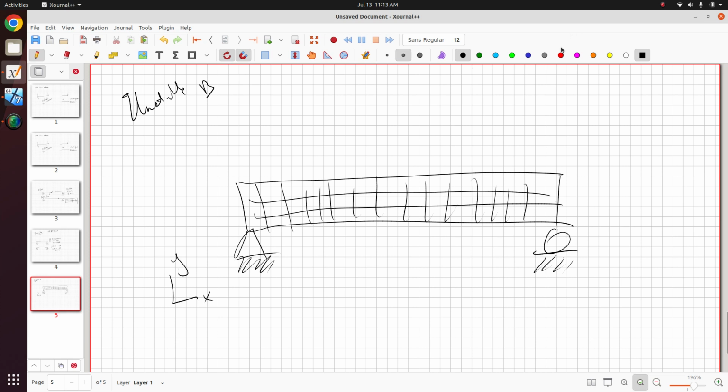Now when you try and perform your statics analysis, you get the error UFM 9050. You ask yourself, okay, what's going on? My boundary conditions yield a stable configuration. What is going on? If you're not careful, the mesh could actually be disconnected. So here, let's see if I can draw it. The red is the deformed mesh, if you will, and the black is the original mesh.